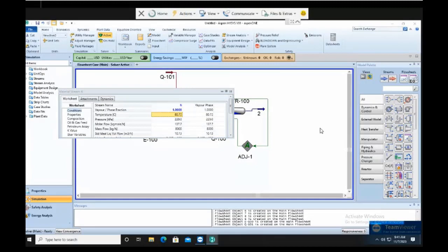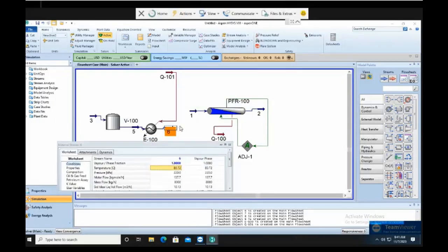But we don't want it to be condensed, because after this you have to increase its pressure. Okay, the pressure to the reactor is 760 kPa, right? 700 kPa. So we don't let it be at 1 because we don't want it to suddenly condense in your compressor. Then it will break. So we know the temperature has to be more than 80.